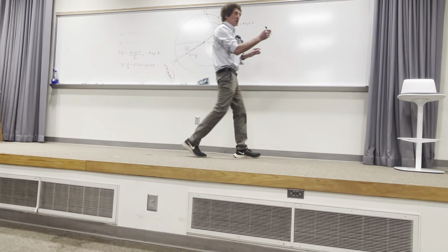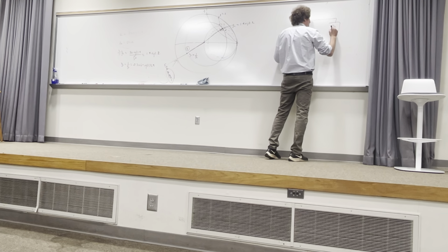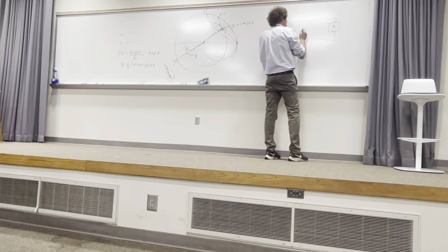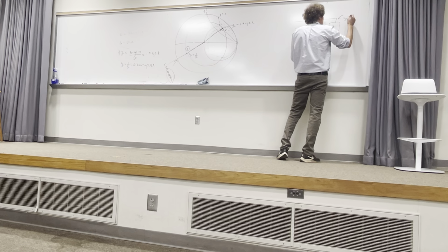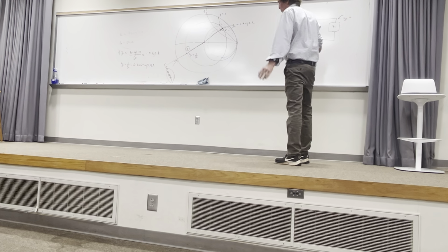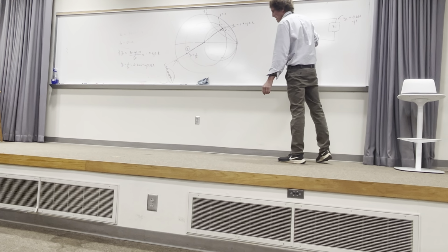Now, remember, we're going to do this, and I should draw it over here. We're going to do this with an open circuit stub. So here's my ZL, right here. Here's my Z0. I've come in, I actually have a normalized Y of 0.206 minus j 0.324.